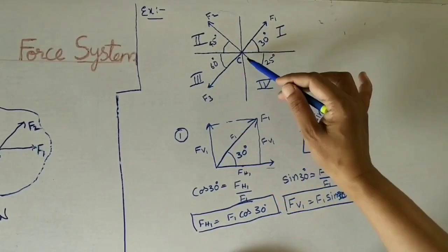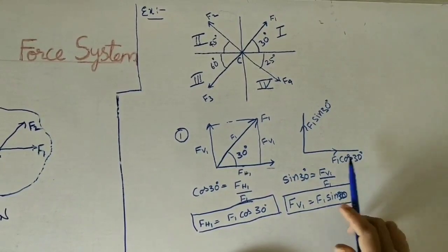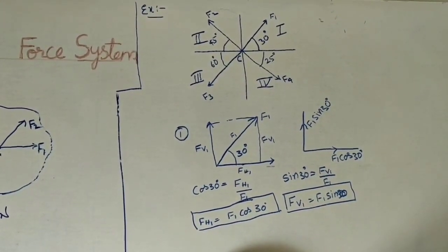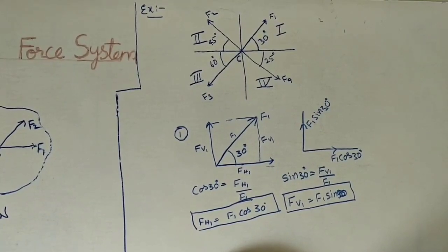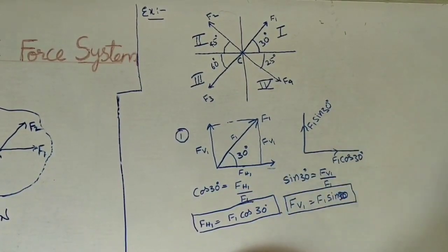Here also one horizontal and one vertical. Like that we have to divide the entire diagram in terms of all horizontal components and all vertical components. This process is called resolution of forces, meaning dividing the inclined force into a vertical component and a horizontal component.